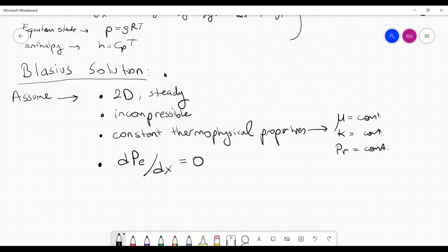The geometry must basically be a flat plate. It shouldn't have any curvature on any of its surfaces, so it should be flat. And you should put that flat plate inside a wind tunnel. Then, if needed, by properly adjusting the wind tunnel cross-sectional area a little bit, you can obtain this condition.